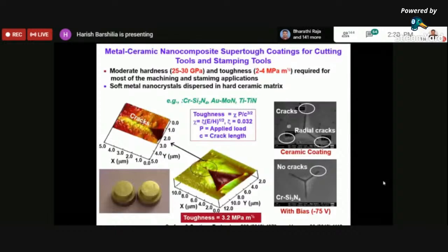The second limitation is the temperature. If you heat diamond to more than, say, 400 degrees Celsius, then diamond converts to carbon dioxide, and the coating gets vanished.